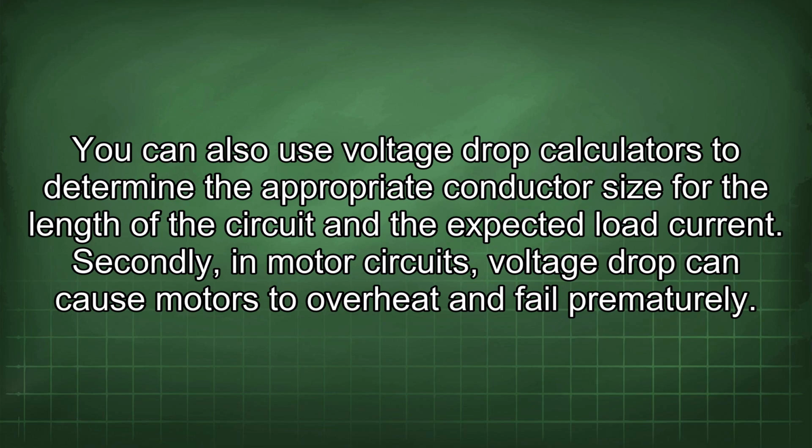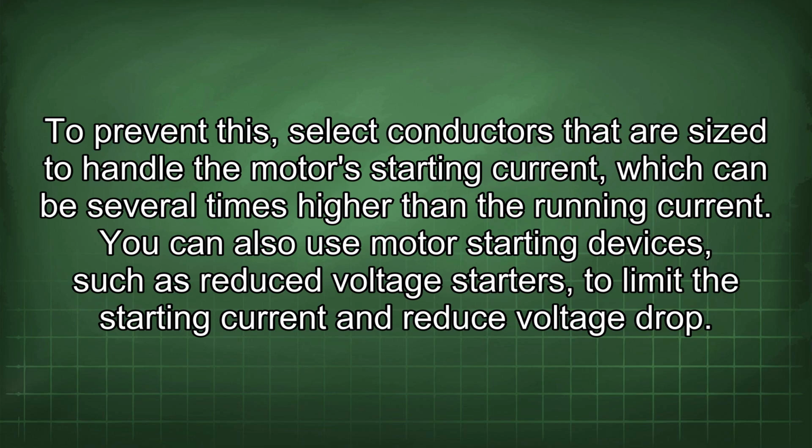the expected load current. Secondly, in motor circuits, voltage drop can cause motors to overheat and fail prematurely. To prevent this, select conductors that are sized to handle the motor's starting current, which can be several times higher than the running current. You can also use motor starting devices, such as reduced voltage starters, to limit the starting current and reduce voltage drop.